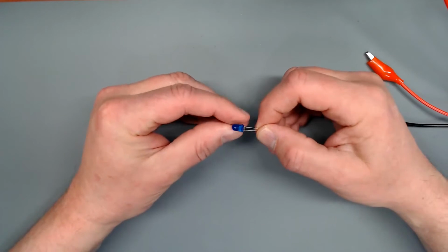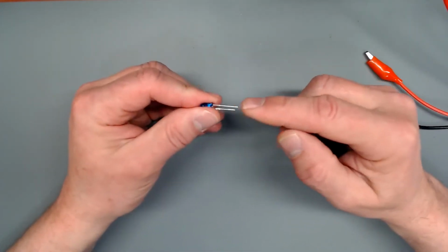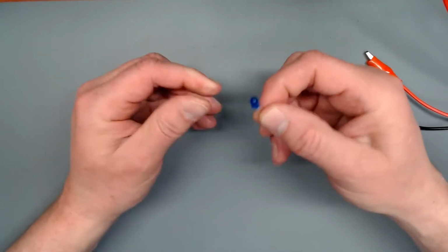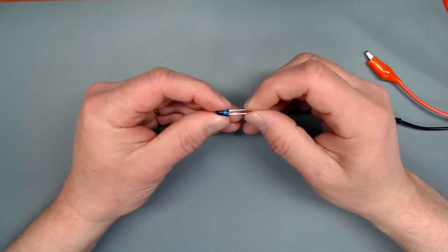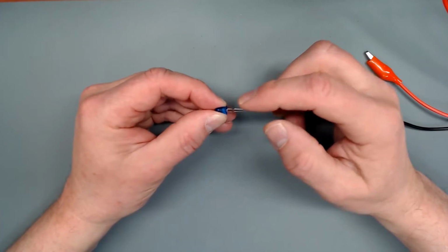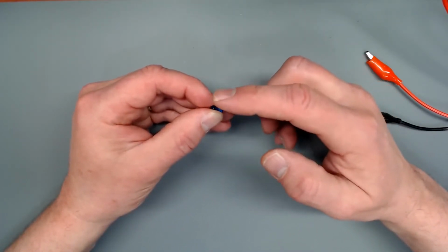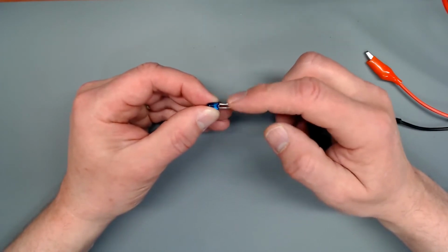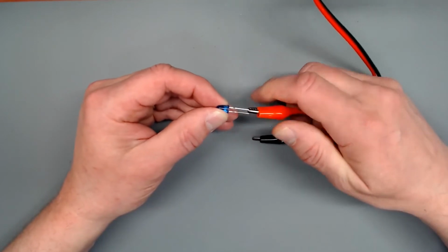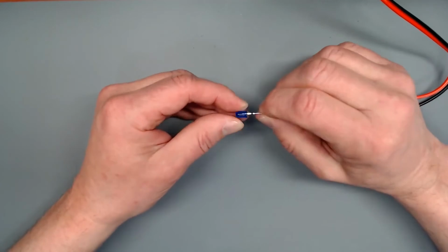Now, to utilize an LED, we have to provide power and current to it. Power in the form of voltage, current in the form of milliamps on these very small LEDs. And the way to figure out which way to wire them, I'll give you a few pointers here. The anode, which is the positive side, is the long leg. And you always think of it this way: long legs are a positive thing. So that tells me right there to put my positive lead on the long leg.